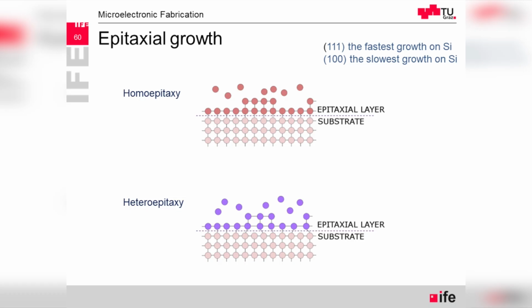So in case of the homoepitaxy, we have silicon, but it could be, for example, that we had a wafer that was highly doped, and then we're adding almost pure silicon. So the reason to do that is it's very expensive, so normally it wouldn't be really interesting. But there is a reason behind, and to add the uniform layer of different doping of the material, and then on this layer of epitaxial silicon, then we build transistors.